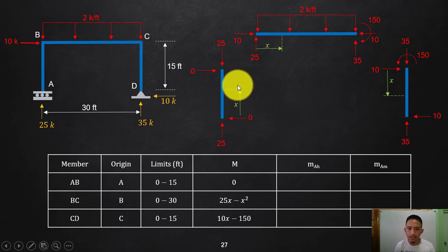So in here, I will cut that one, and what will be the moment there? Actually, there is no moment because that is a force going to the point, or that is a concurrent force. So there is no moment of those. I am considering this part. Okay, if I cut that one, that is 0, so there is no moment. There is no moment horizontally. There is no moment due to that horizontal force. So actually your moment equation there is 0.